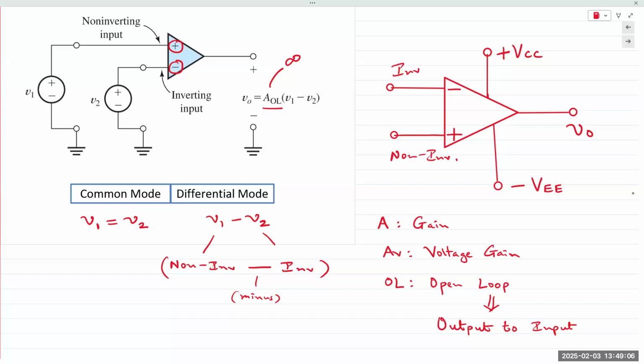So if you have a differential amplifier like this, any noise signal that's present in the surroundings of the terminals will appear equally at both terminals. So if we can attenuate the common signal that appears at both terminals, we can completely reject any noise signal that comes at the terminals. And only the difference in signal is amplified. The common signal is rejected.